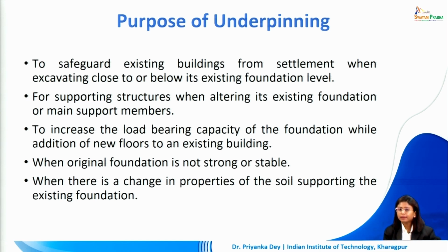Now say we had considered a certain bearing capacity of the soil for that calculation, and over time something has changed because of which the soil no longer has similar properties. That means the factors of safety and other parameters we had considered while calculating the size of the footing are no longer applicable. Probably now we need a deeper foundation.